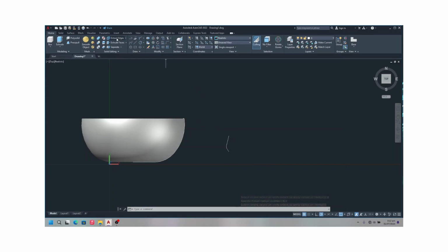Now all you have to do is mirror it. Just type in mirror and select the objects you want to mirror. Enter, and then specify the axis in which you want to mirror. Array source, no, yeah. And there you go. That's your first petal. Now we're just gonna join all of this into a single entity.